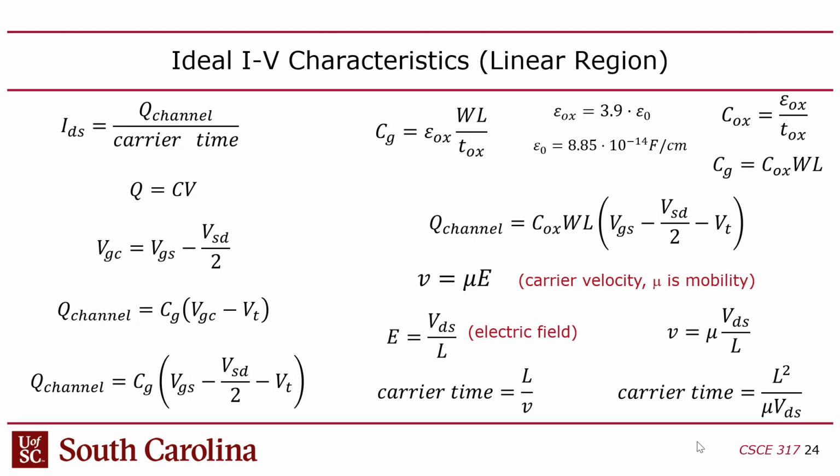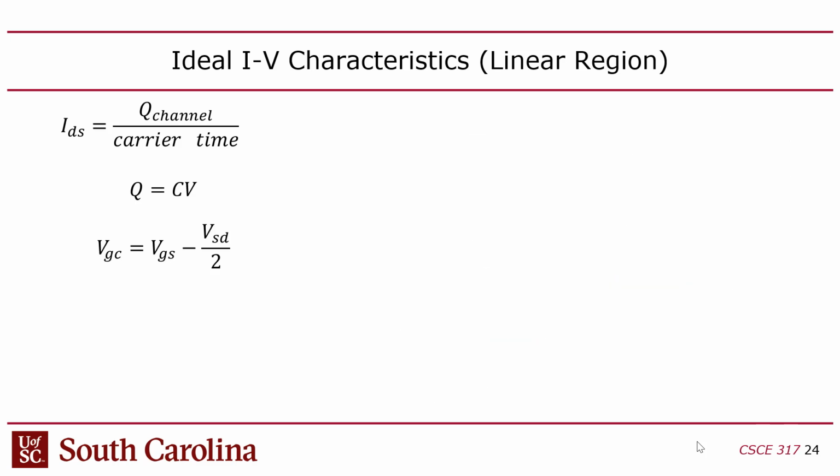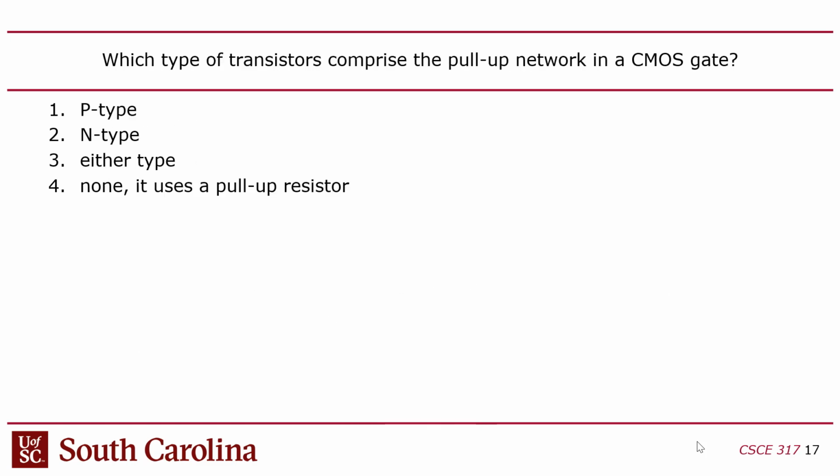That's the channel length. The width, on the other hand, is something we don't want to necessarily use minimal size all the time on. I mean, if we make it minimal, then the transistors are minimal size and we could fit more of them, right? But if you make the width bigger, you get more current because, let me show you, let me back up here because I think this is an important point.